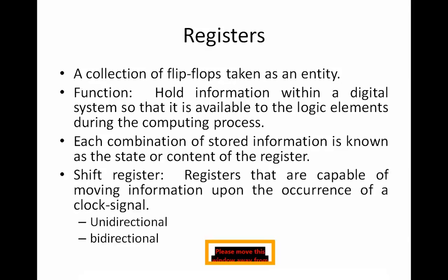Now for your first topic, we will be looking into shift registers, which is nothing but moving data from one point to another point. There are four types of shift registers: PIPO, SIPO, PISO, and SISO, which is parallel in, parallel out, serial in, parallel out, parallel in, serial out, and serial in, serial out. Based on the type of inputs and the type of outputs, we decide what type of shift register this is.